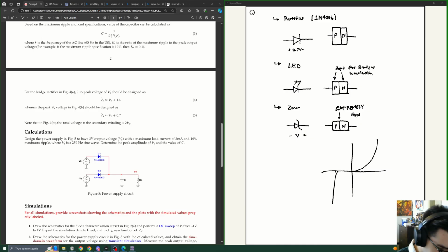So we place the diode in reverse bias, right? And then as long as some amount of current is flowing through it, it actually keeps the breakdown voltage across it consistent. And this actually opens up a really useful use case where we can use it to sort of lock things to a certain voltage, right? Which might actually yield a sort of potential voltage regulator, which we'll talk about in an application next.